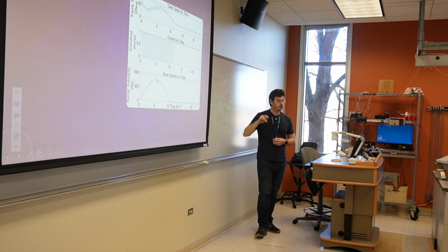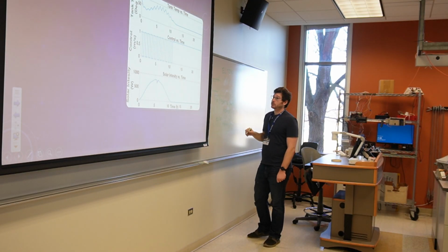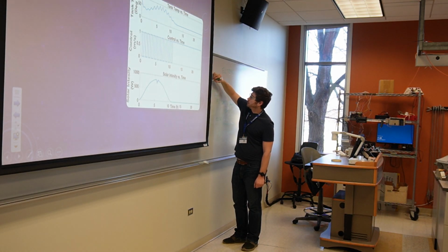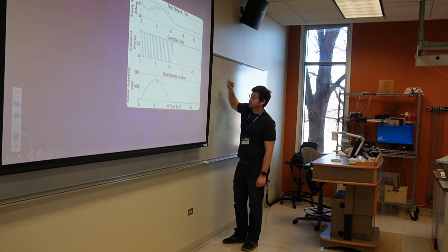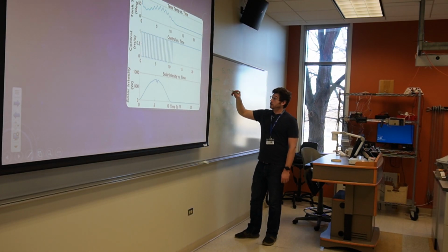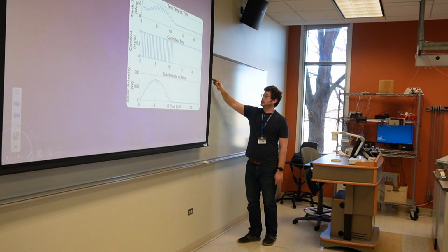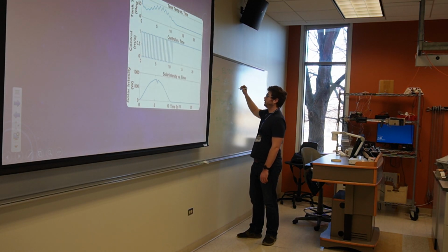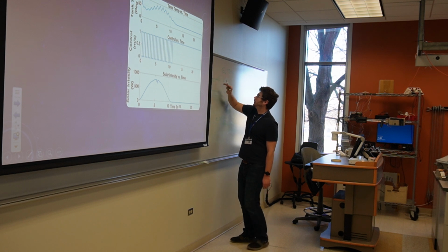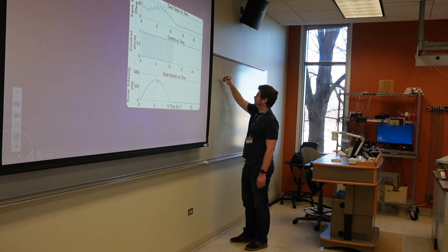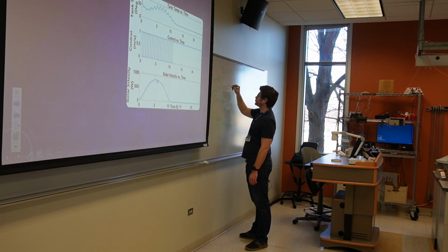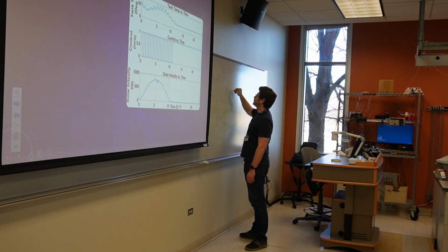It's noisy, okay? When we have bang-bang temperature control, every time it goes under and over our set point, our relay is going to click on and off. This can be fine if this change is pretty slow, right? But if it's fast, if it's a high frequency change, we can wear our relay out. If we're really super zoomed in, for example, I'll make a thicker plot over here. If it really hovers around the set point here, if we zoom in here, and this is what it's actually doing,